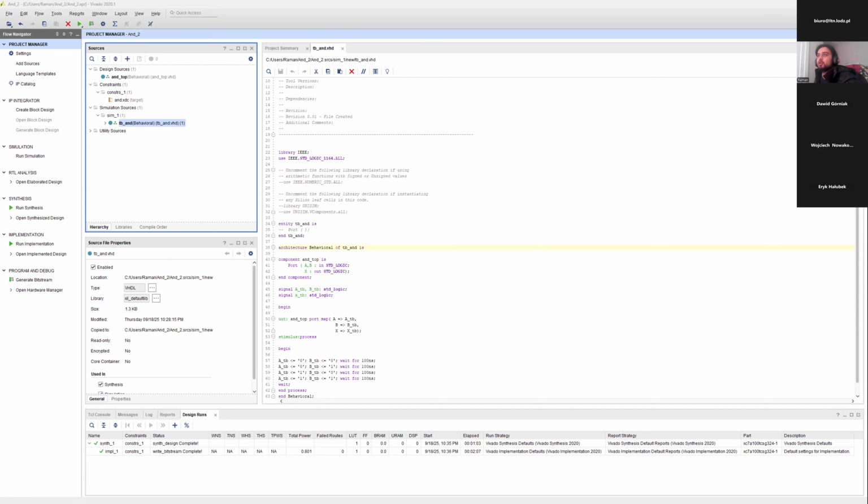That is where you will have multiple modules in the design source, and at that point, you'll need to have your top module set as top. Essentially, the module that is calling everything else has to be set as top, otherwise your code won't work, because Vivado reads the code that is not the top first, and that causes issues.